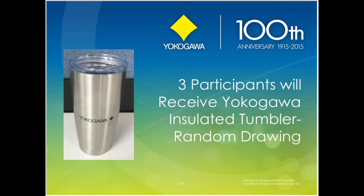James Albritton has a question: what do you use to perform wake frequency calcs? We have a form that we can respond to you with. It basically asks you for all your process information and what your thermal well design is. We take all that information and use the wake frequency calculation for that, so we can send that to you. Basically, your process information and the type of thermal well you're looking for are used to come up with that wake frequency.